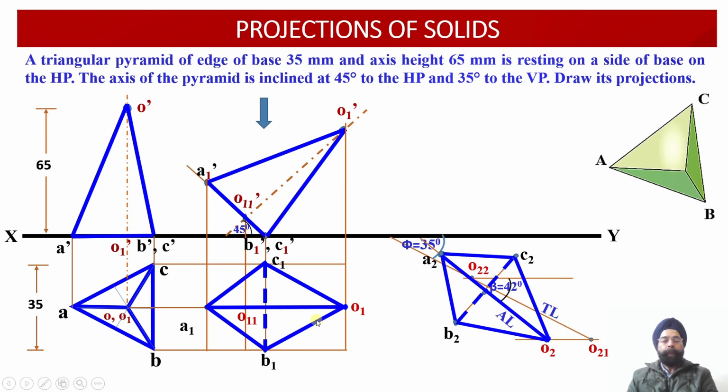So having obtained the plan projections, now the corresponding front view projections of this oblique solid need to be obtained. How can the corresponding projections of the elevation be obtained? Once again, as we are going to look at the solid from this orientation, we have points 1, 2, 3, 4 and 5 available with us. From these 5 points, what can we do?